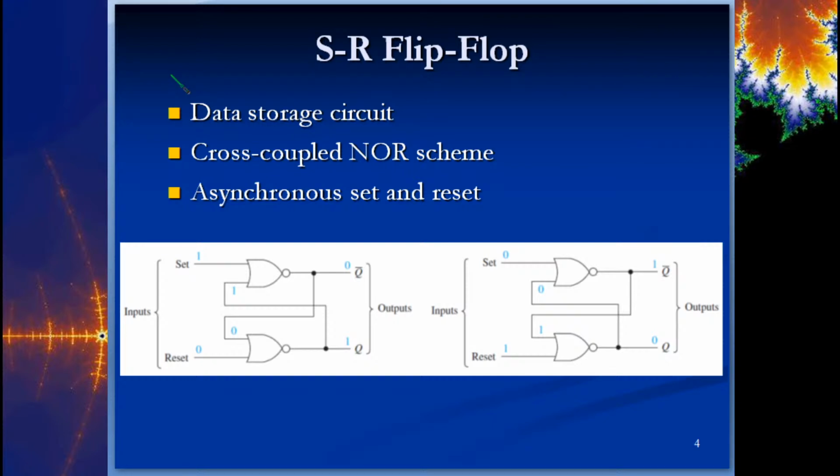Okay? So, yeah. So prior to us talking about flip-flops, we didn't have any way to store any ones or zeros if we wanted to do that, or to recall whether something was high or low. Okay, so up till now we have just used what we call combinational logic, where you can have a lot of different gates feeding into other gates, and then ultimately you have 1 or 2 or 3 separate outputs. Okay, or you just have a single output, right? You could have 10 gates that funnel down to a single output.